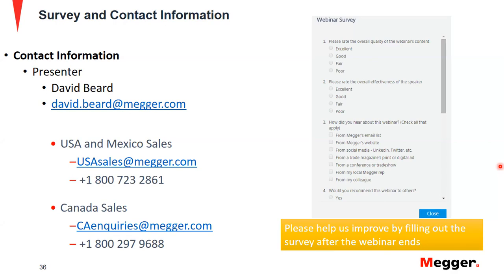So for example, if a 51P and a 51G element are both sitting on the same output contact, usually the 51P element would have a higher setting because it's related with the phase side of the system, whereas the 51G would have a lower setting.